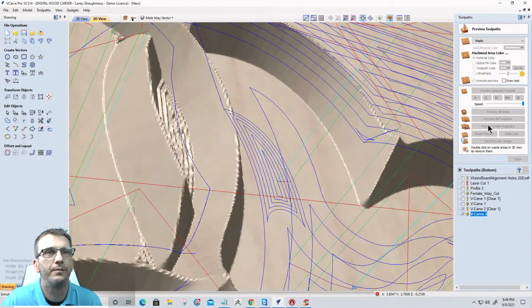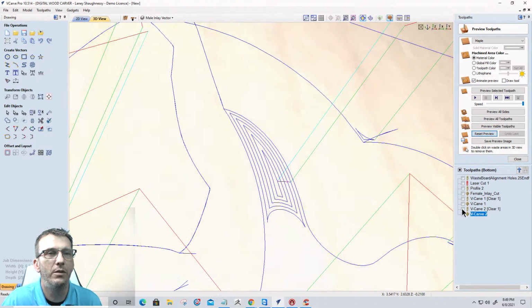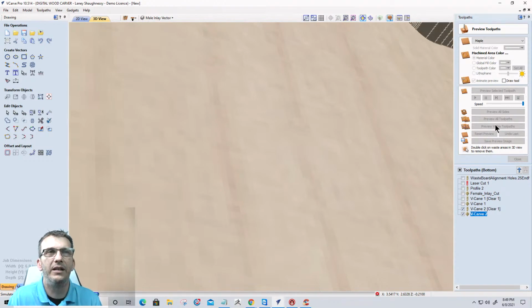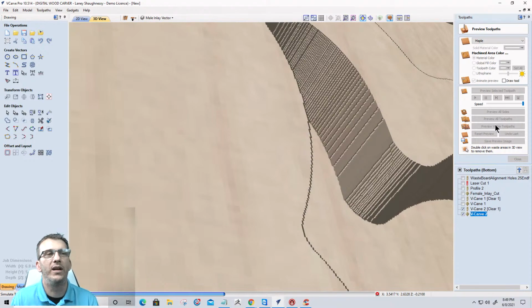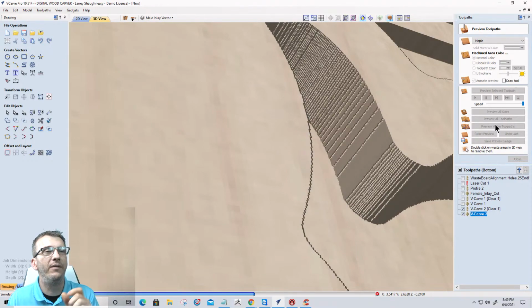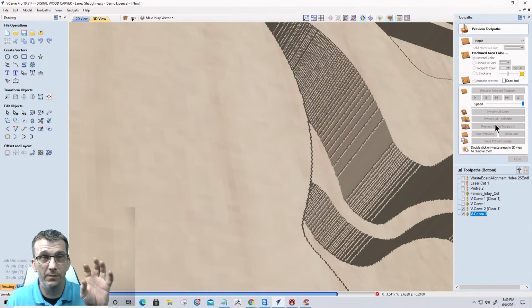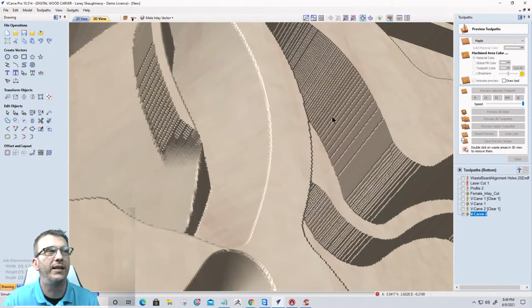Let's preview. Sorry, hold on. Stop. Let's reset the preview and preview the visible toolpath, because I really want to make it clear what could occur if you exceed your cutter's length. And I have definitely, in this case, exceeded my cutter's length by quite a bit. We could see it when I exceeded only by a few thousandths of an inch, starting to create that straight meat, but we'll be able to see it definitely in here. If I was trying to do a 0.3 cut depth, I would have to change my V-bit, because my 60 degree 0.25 V-bit just won't cut it.